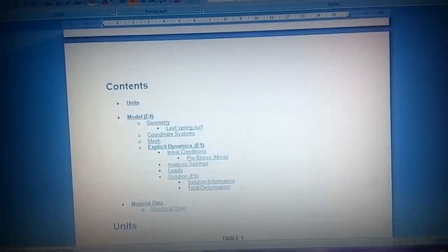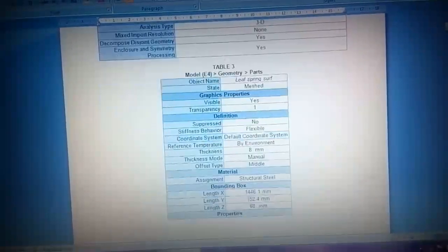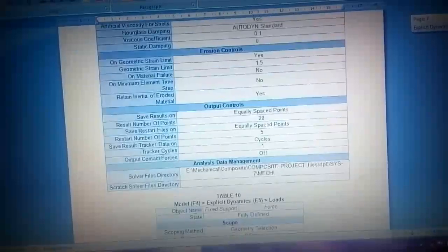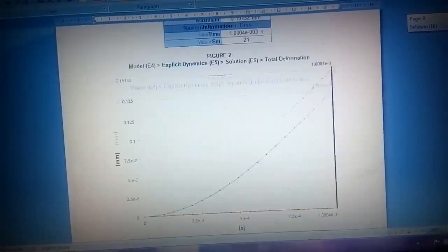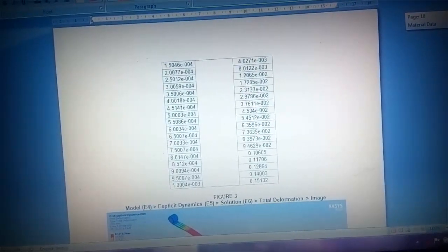The first layer and last layer are E-glass fibre. Between them, Aloevera and Roselle make up 6 layers. The epoxy resin is added between the layers. It acts as a gum to create the composite material.